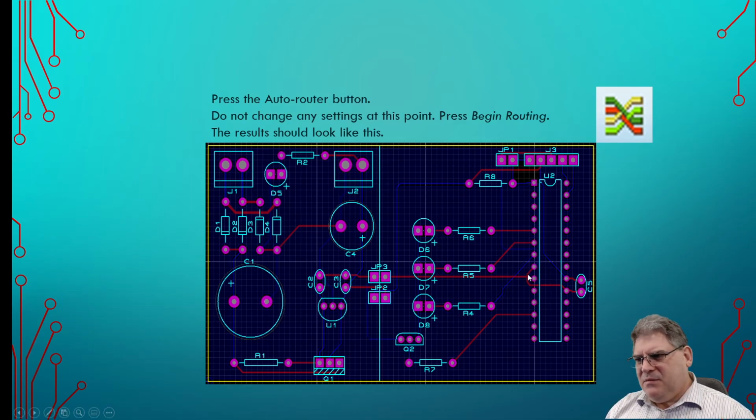But yeah, speaking of why you wouldn't want the ground to go through a pin, if something ever happens to this pin, or you do have a lot of current running through it, it will heat that point up. Or if you were to be removing that chip, you could damage it and end up with a problem. So star points are a good idea. The star point is where the power basically comes in and then branches off into multiple places.